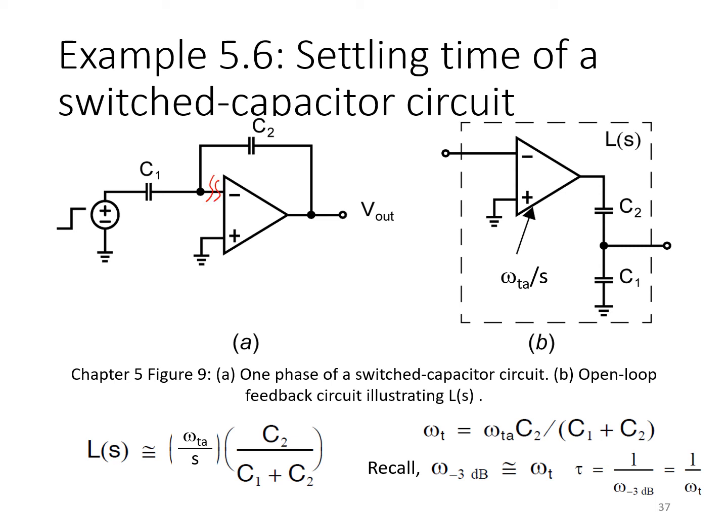Doing so gives rise to the circuit shown on the right, where we've simply got the single stage OTA here, whose frequency response can be modeled at frequencies around its unity gain frequency by this simple expression here. That's our integrator model for a first order, single stage op-amp.